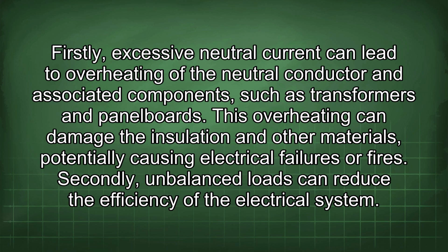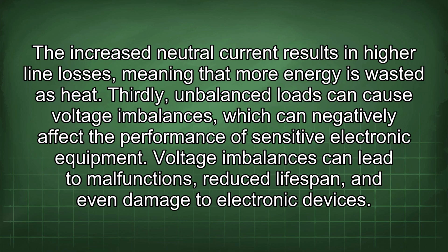Secondly, unbalanced loads can reduce the efficiency of the electrical system. The increased neutral current results in higher line losses, meaning that more energy is wasted as heat. Thirdly, unbalanced loads can cause voltage imbalances, which can negatively affect the performance of sensitive electronic equipment. Voltage imbalances can lead to malfunctions, reduced lifespan, and even damage to electronic devices.